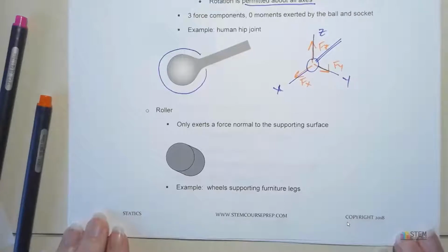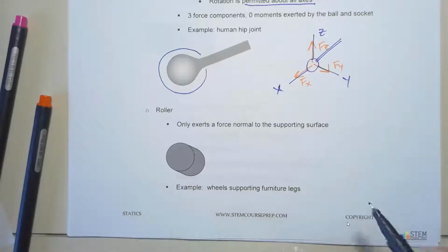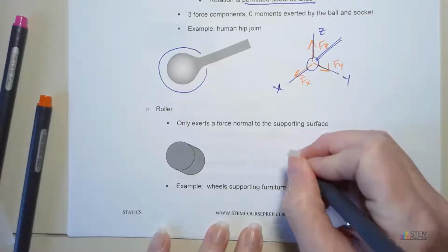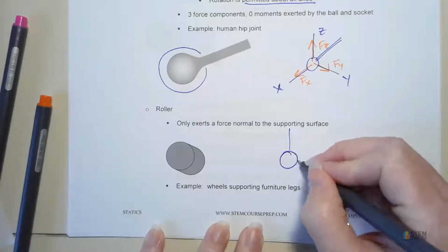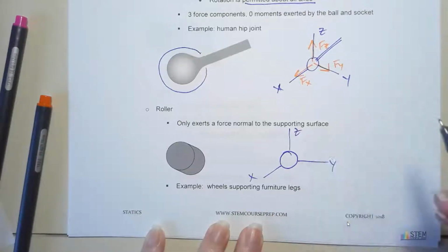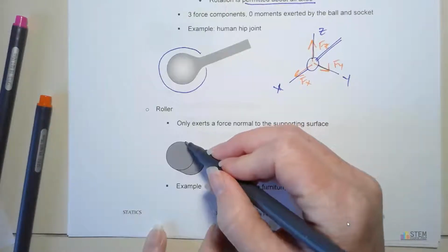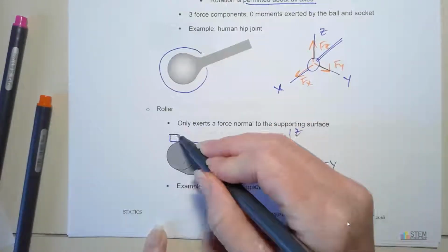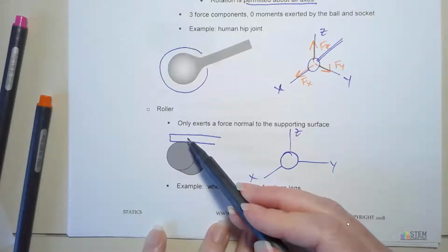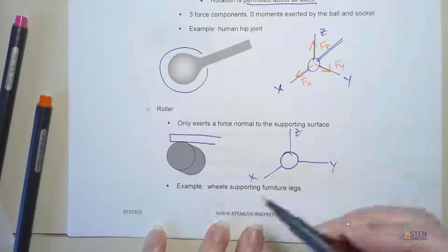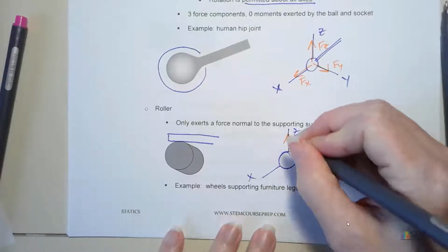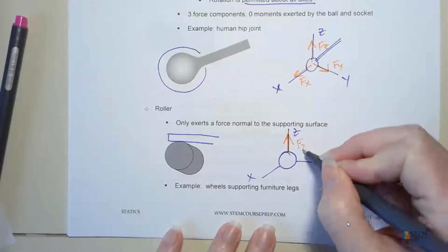A roller, we talked about rollers before with the 2D system. Same thing for this one, for 3D. So if we were to draw the free body diagram, let's draw our coordinate system. Let's say that's X, Y, Z. If I were to put a mass up here, this roller, all it does is it supports this mass. All right, the mass is just sitting on that roller. So essentially the roller just provides an upward force. All right, so that would be FZ.